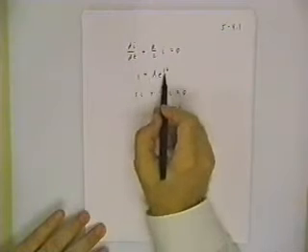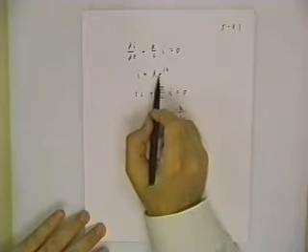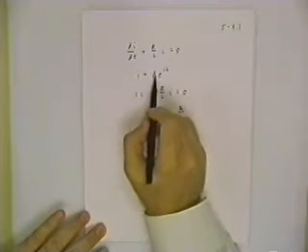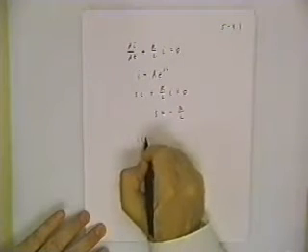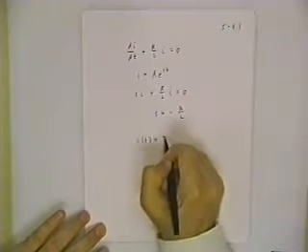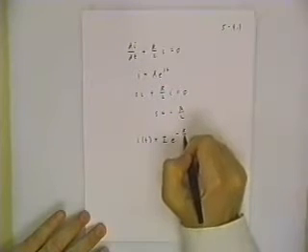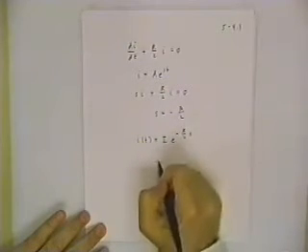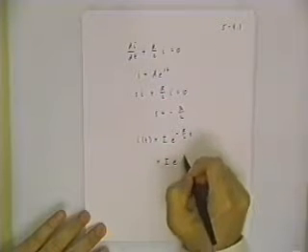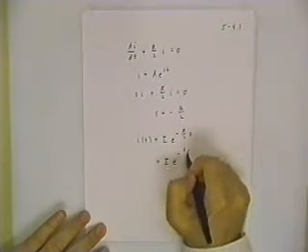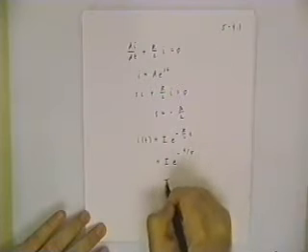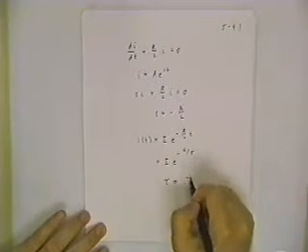And the initial value of current we can read right off of the problem statement. At t equals 0, I is equal to I amps. So we can quickly come up with the final solution, which is capital I times e to the minus R over L t. And if you put that into the time constant form, e to the minus t over tau, where tau in this case has to be L over R.